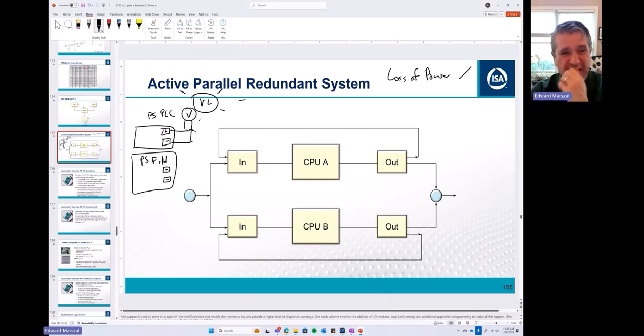And you should do that whether you're doing an energized to trip system or a de-energized to trip system. But for an energized to trip system, that alarm telling you that your safety PLC power is gone is a requirement instead of a nice to have, as it would be for a de-energized to trip system.